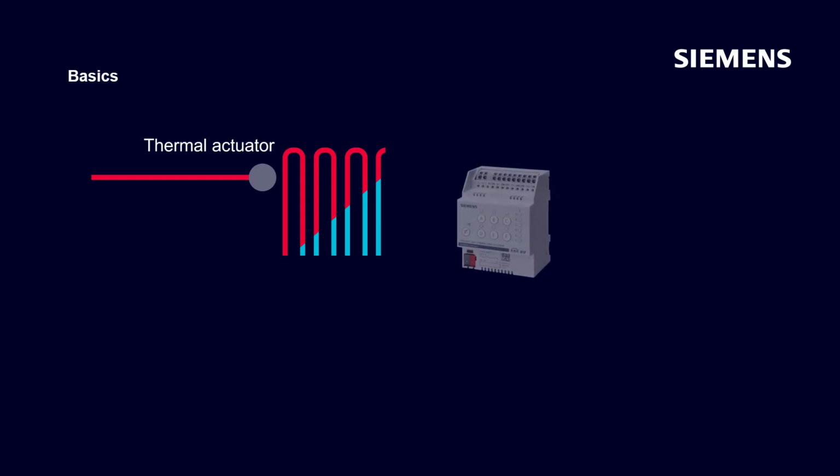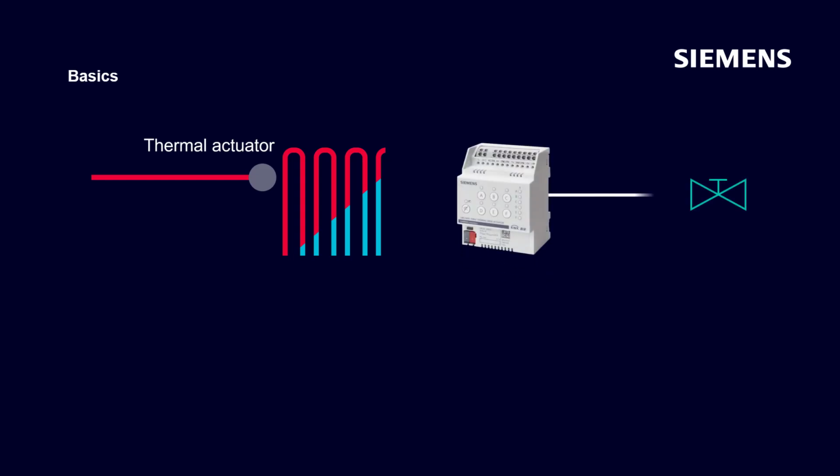For demand-oriented, energy-efficient individual room temperature control, thermal actuators are required at the respective heating surfaces. The valve's opening or closing regulates the hot water's flow rate and, thus, the heat output in the rooms. Thus, each room receives the desired individual room temperature. The control of these thermal actuators is realized via a corresponding KNX-based actuator technology. This guarantees a customized temperature control. The comfort, the usage behavior in the room, and the energy efficiency are optimally coordinated.